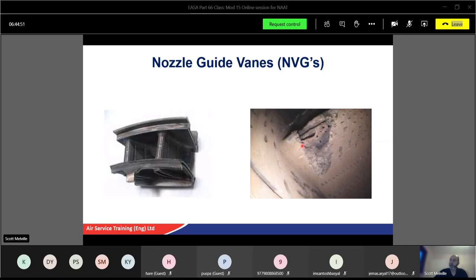That's going to cause aerodynamic losses and disturbance to the airflow in the turbine, which could cause a bit of vibration, and eventually this could actually break away. And where's that going to go? It's going to hit the turbine. If you're lucky, small bits at a time, and the turbines can chew them up and spit them out, that's fine. But if there's no cooling protection, that hot gas is just going to burn it away, so the cooling holes won't do their job anymore. And because of the low cycle fatigue, cold, hot, cold, hot, they will eventually crack and get worse.